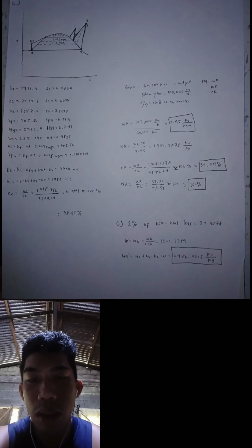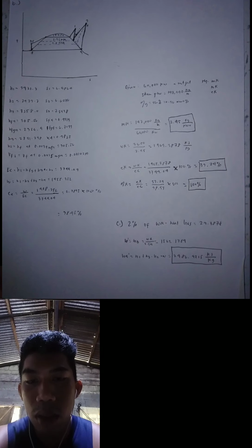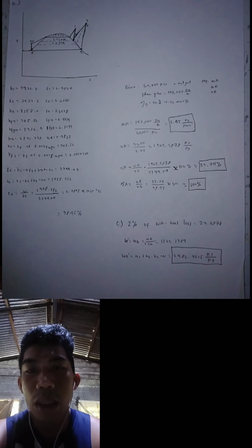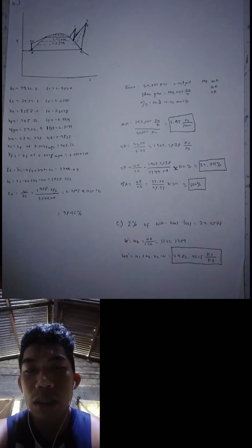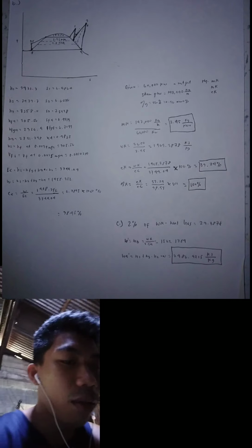Enthalpy of steam entering the engine minus enthalpy of saturated liquid at condensing temperature is equals to QA is equals to H1 minus HF5 plus H3 minus H2 is equals to 3,744.04 kilojoules per kilogram. Work is equals to H1 minus H2 plus H3 minus H4 is equals to 1,458.352 kilojoules per kilogram. And for the e is equals to work over QA is equals to 38.95%.